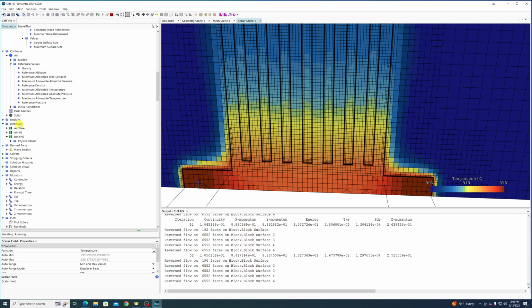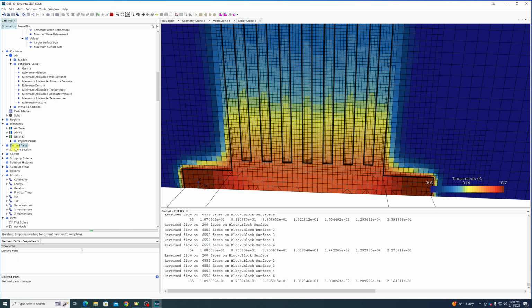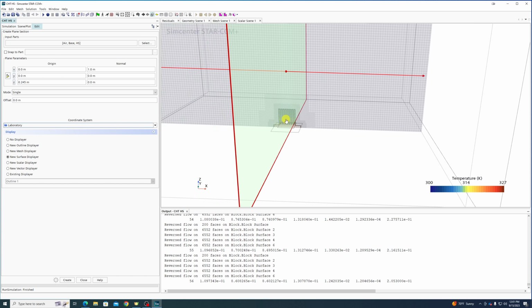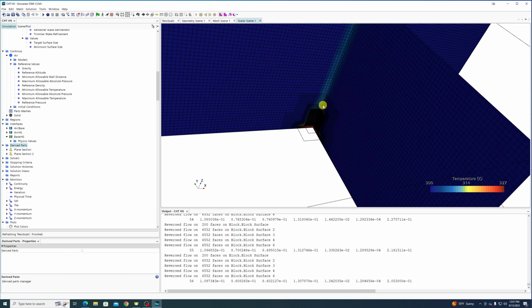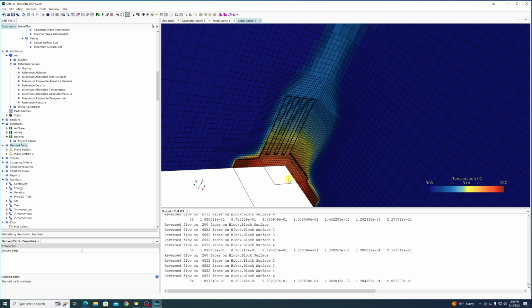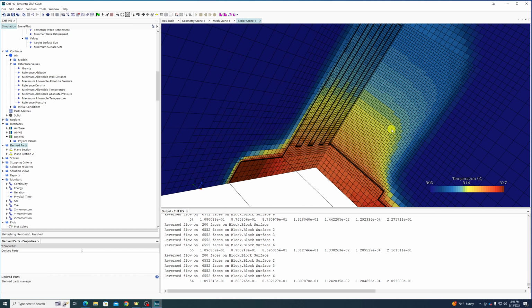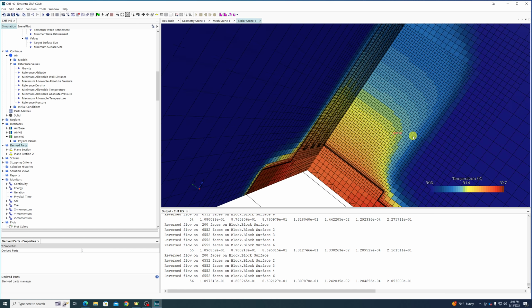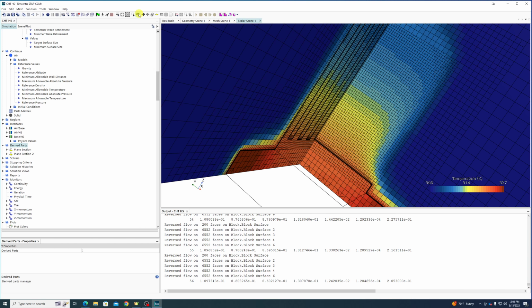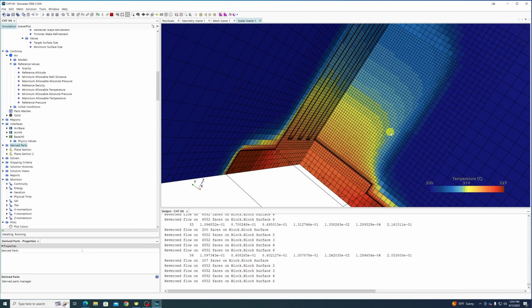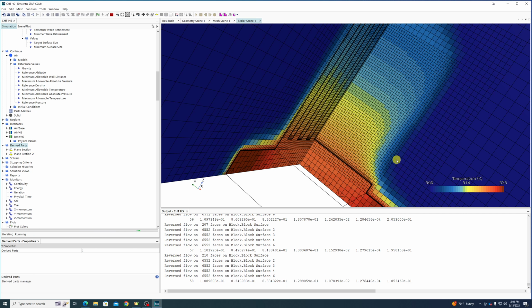And we can verify that this is truly three-dimensional by stopping the simulation for a moment, creating a new derived section plane, and adding it to our existing scalar displayer. We can see that this has two directions, very definitively. We can actually see what the thermal profile looks like inside the air gap in between some of these fins by looking at this profile here.